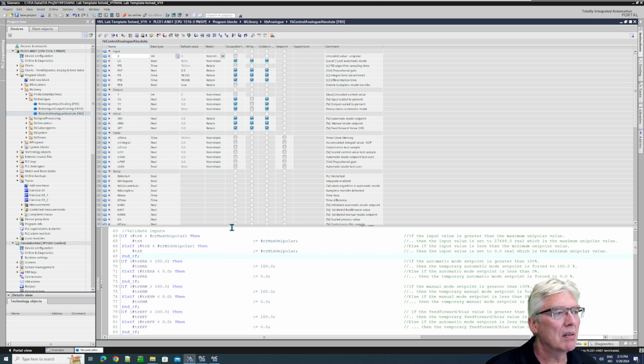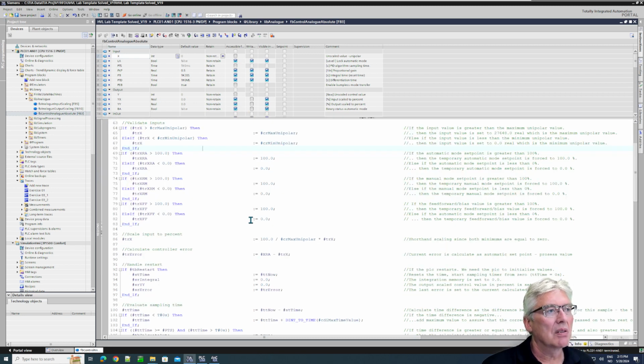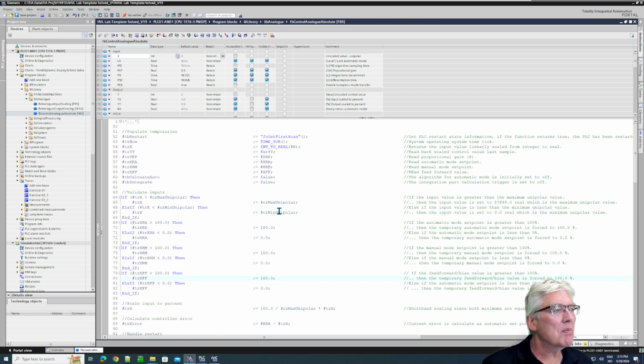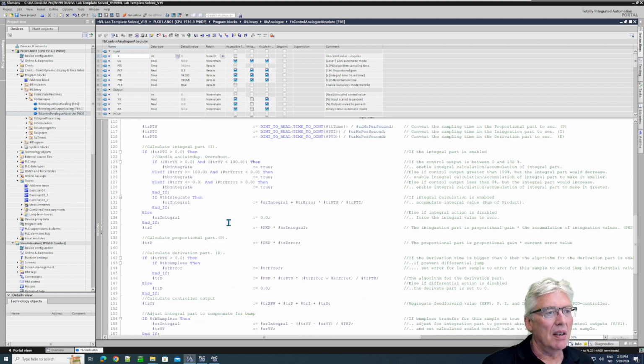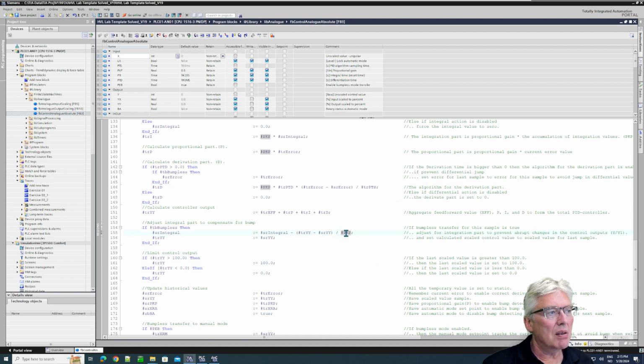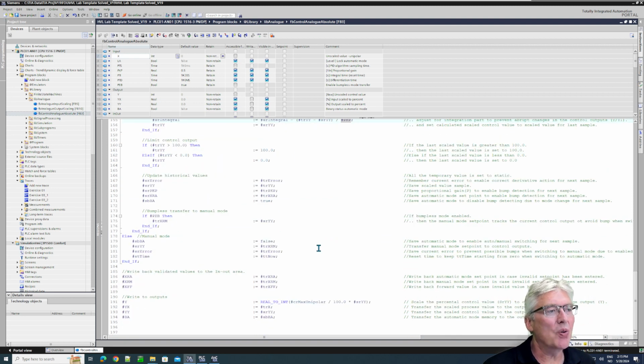So far, you should have detected yourself, there is one, it seems, if someone gives me a gain here of 0 in the algorithm, I would divide through here. If I have a bumpless, here would be a division by 0, which is not nice, and you should fix it. There is an error, a small error in this program. Intentional? Maybe.